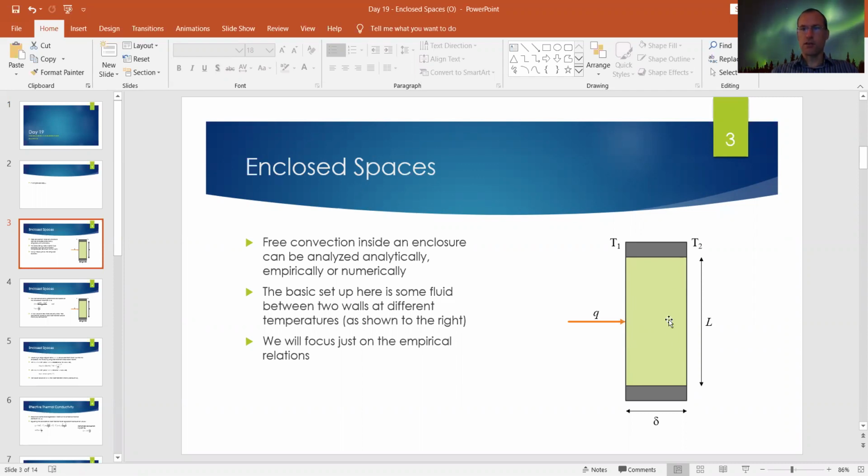And then as you get this current going down on this side, going up on that side, eventually it hits the top and bottom because, as I said, it's an enclosure. So there are actually borders on the top and bottom. Before, when you had a flat plate, it just kept on going up. Here it gets stuck and basically gets turned around, comes over to this side, then gets pushed down from the cold current, gets pushed over to this side, pushed up. So you end up having this recirculating flow coming through here in this situation.